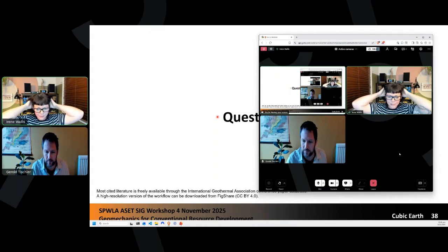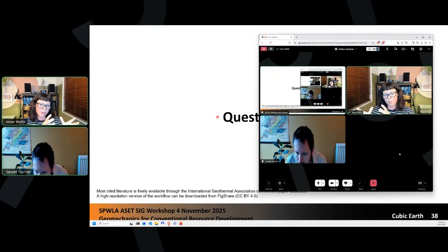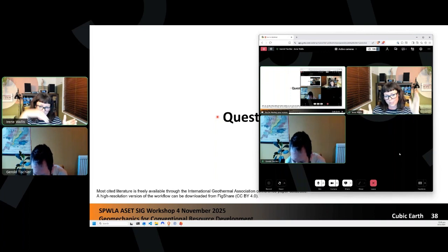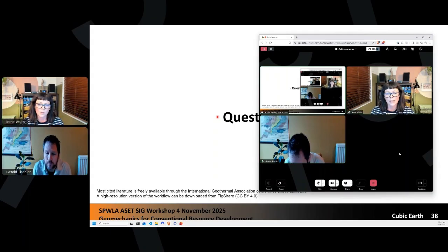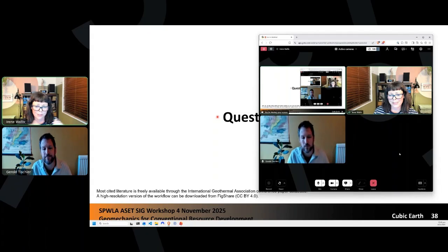So when you say acoustic logs, there's acoustic borehole images, where you're sending out a waveform, you get it pinging back, so you have a change in amplitude and you have a change in travel time. And we use a lot of acoustic borehole images in geothermal, and we're often using the travel time signature to determine if things are actually open at the borehole wall.